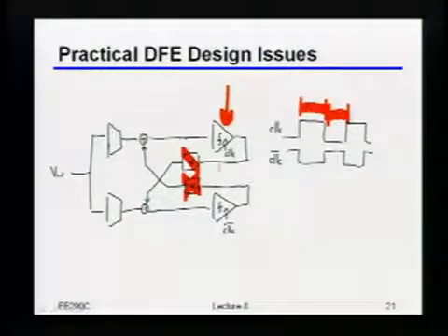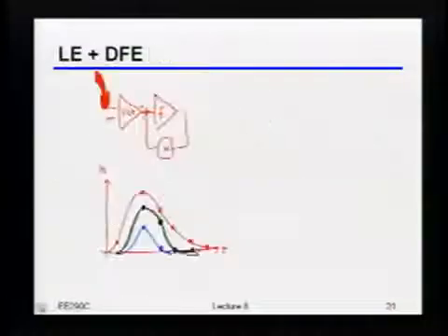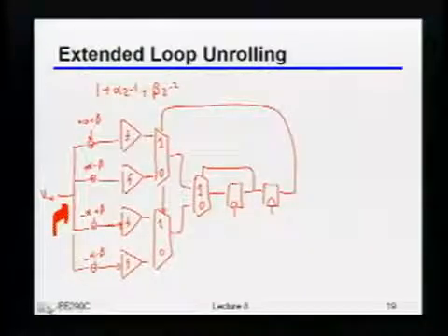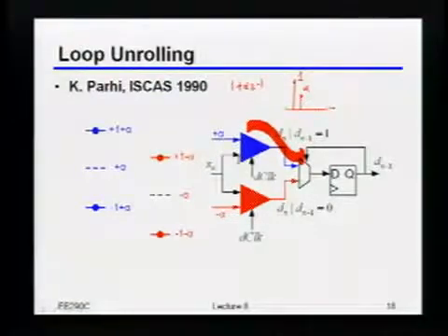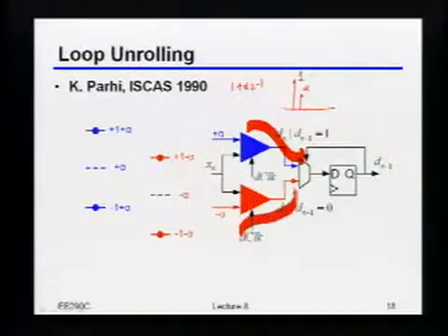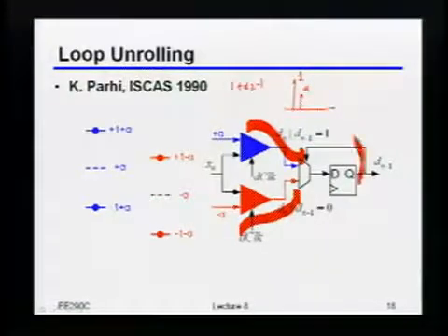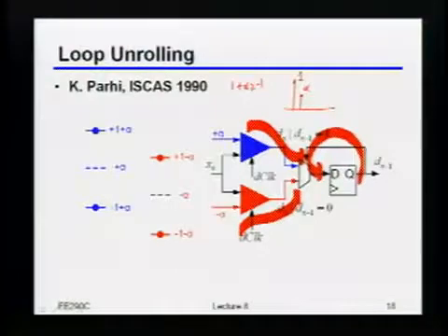Well, imagine that I wasn't doing any DFE at all. If I wasn't doing any DFE at all, that's clear. If I'm now doing DFE, then you're right, to actually see it you have to walk through the timing path for the loop unroll. But it turns out that as long as this forward path is not the critical one, you're somewhat insensitive to the delay of the comparator, because you're going to be getting a delay from the comparator on the other way. So as long as they arrive at roughly the same time, and this forward path isn't the critical one, they don't really eat into this feedback path. That's kind of what it comes down to. Again, that's under the assumption that the feedback path is the critical one, not the forward one, which may or may not be the case.